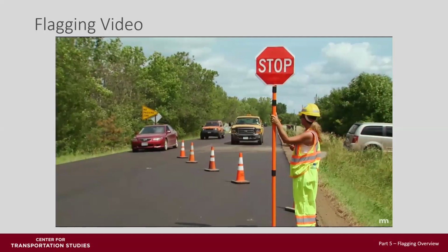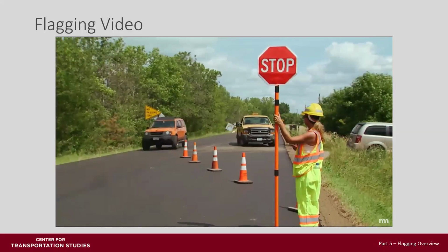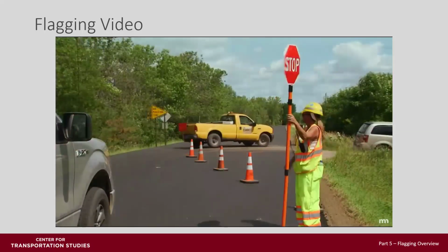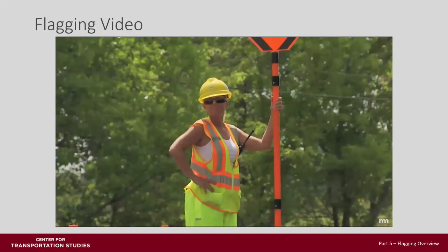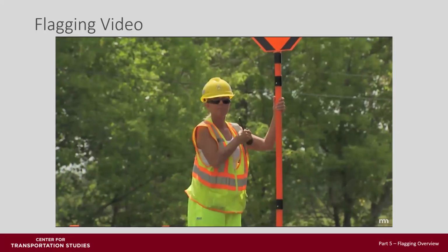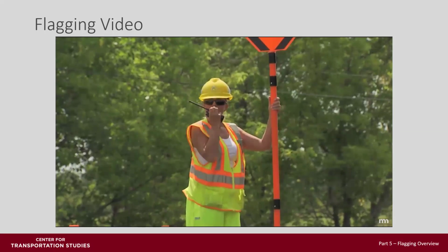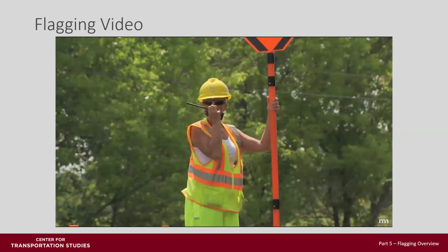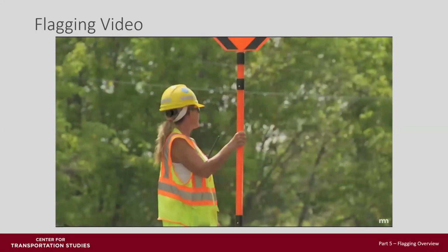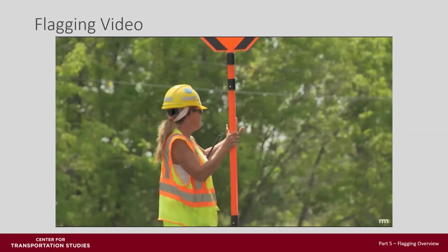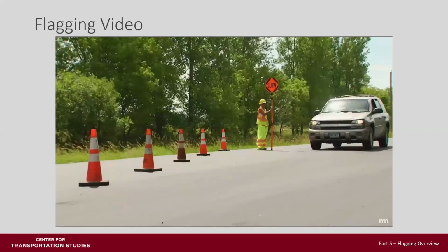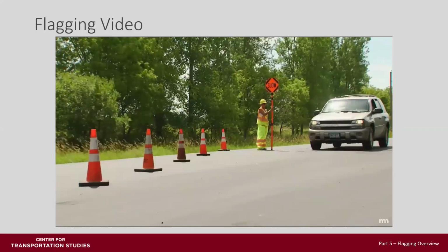When the flagger has determined that the last oncoming car has gone through the work zone, the pilot car should turn around and lead the opposite direction of traffic through the work zone. The flagger should describe the last vehicle to the other flagger after the last vehicle is allowed to enter the work zone. Vehicles arriving late to the flagging station should not be allowed to proceed if the last vehicle has traveled more than 300 feet beyond the flagger station.